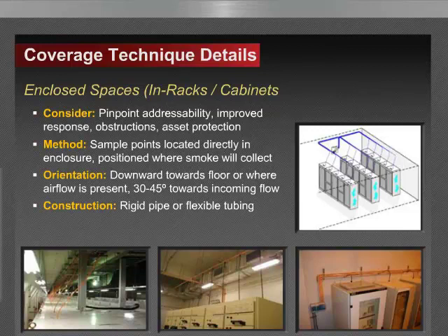the incoming airflow. And the construction can either be rigid sampling pipe or small bore flexible tubing placed within the cabinet, positioning the sample port within the cabinet. And where there's a need to have pinpoint addressability, consider aspirating smoke detectors capable of addressing to an individual point or dedicated detector in that manner.